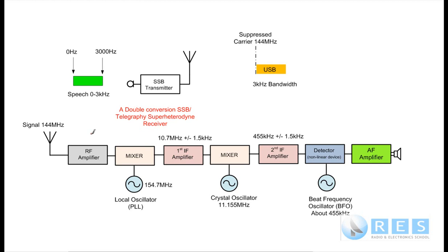Well, you don't want to have to do that all the time, so we have a feature built into our receivers called AGC, which stands for Automatic Gain Control. And the way AGC works is we take a little bit of the signal out of the RF amplifier, and it's a radio frequency signal, and we turn it into DC with a diode, and we add a little bit of filtering to the output of the diode, and that will produce a DC voltage here.